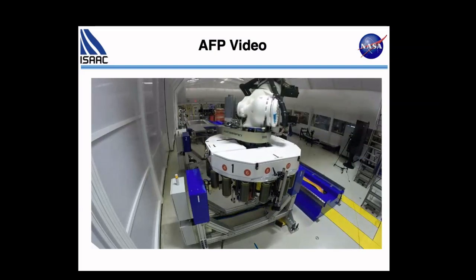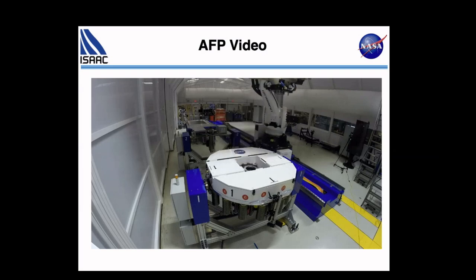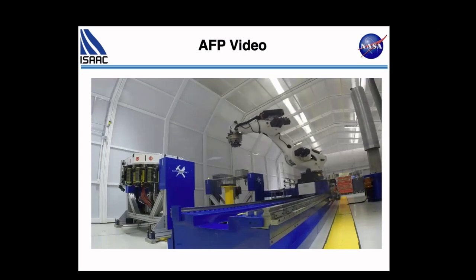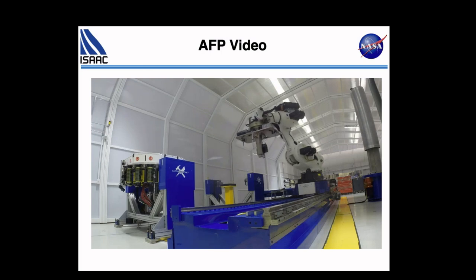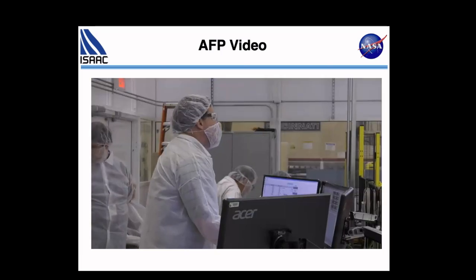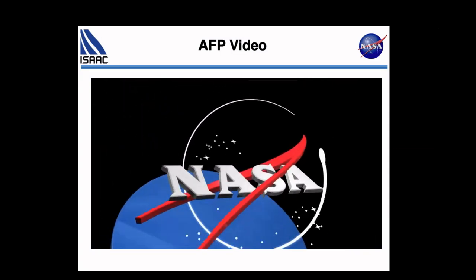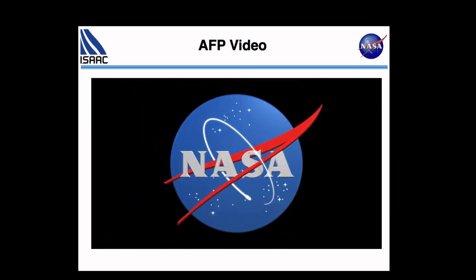When we want to set the head down, we put it in our transfer stand. Very quick process. And then we can go up and pick up a different head. The video doesn't show our stitching head, but I'll use the example that's here, where we can go over and pick up a different head, and then we can go over and use that. Very straightforward process. We have an ultrasonic knife that will cut a pre-programmed path in what we call the green material, the material that we've just placed on the table. And that can be very useful if you're trying to get a shape that isn't something that's easy to program, or if you want to cut out a circle or something out of your part.